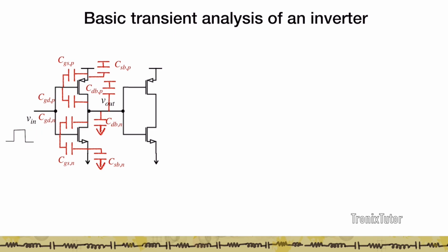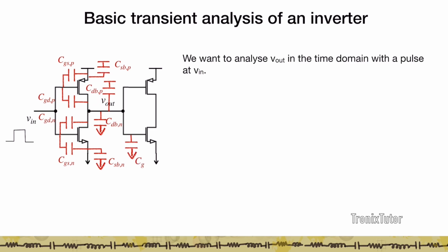Now in this graph, if I look at this very simple inverter of two transistors, based on what we have discussed about capacitance modeling in the MOSFET, you see that there are multiple capacitances that come in when these nodes transition. So remember, V in is changing and similarly V out is changing. And so you have these multiple capacitances which contribute to the capacitance at these individual nodes.